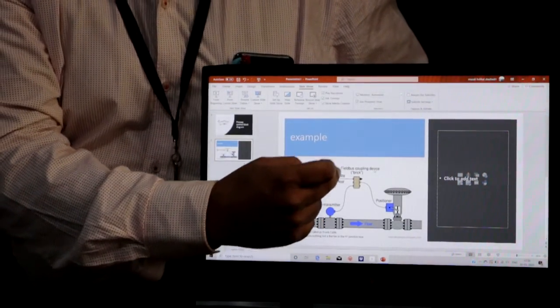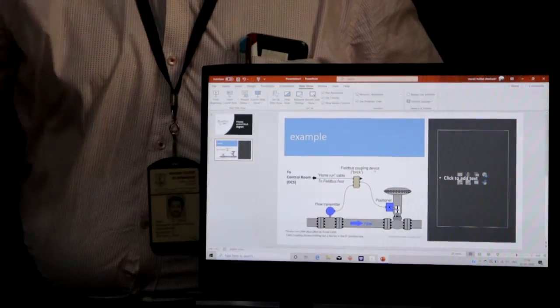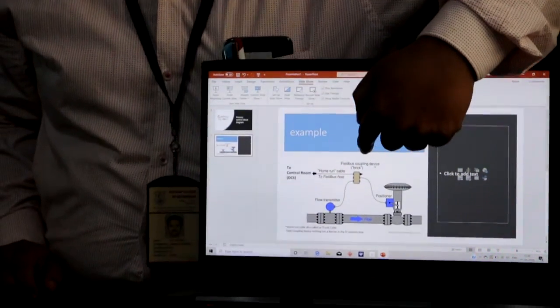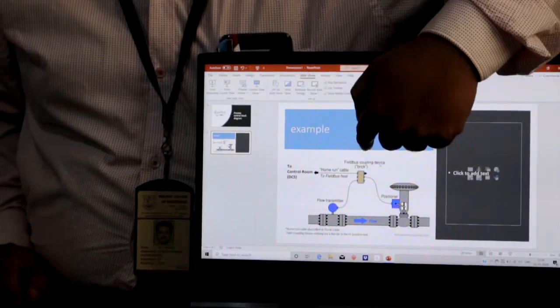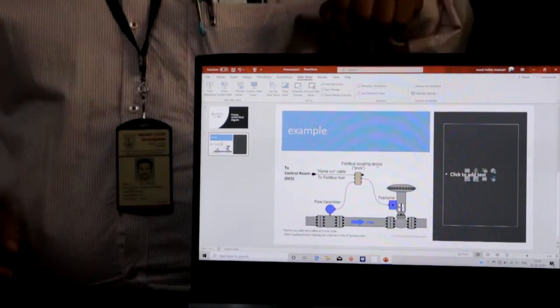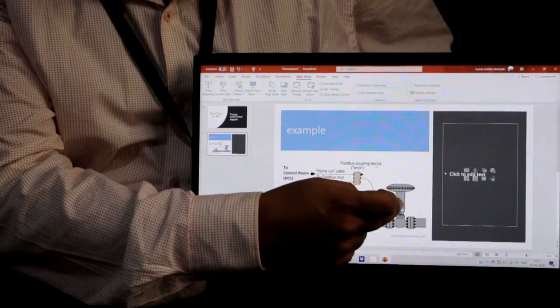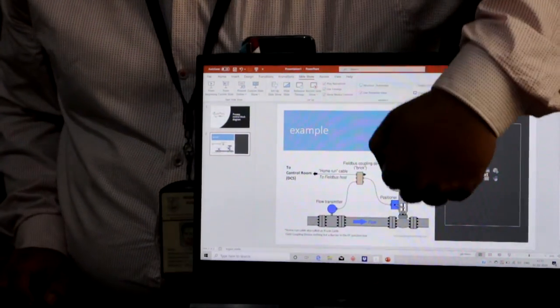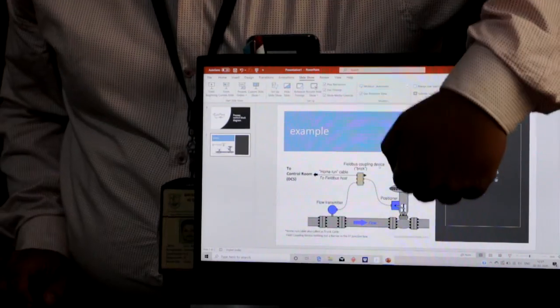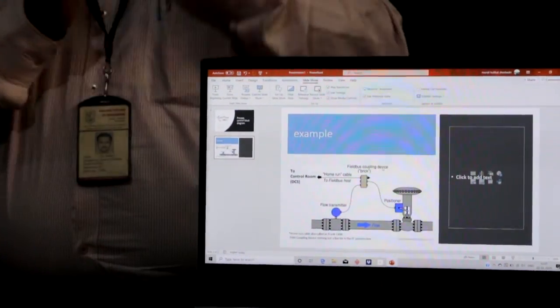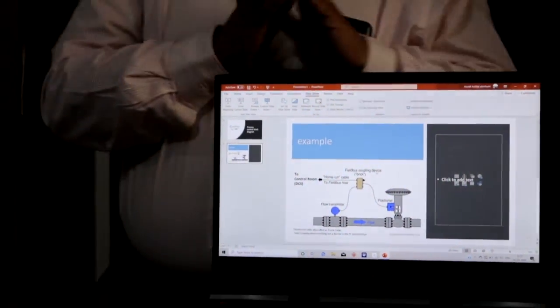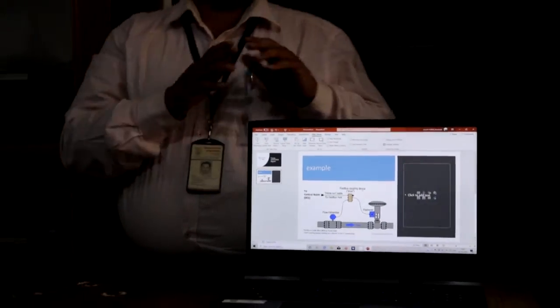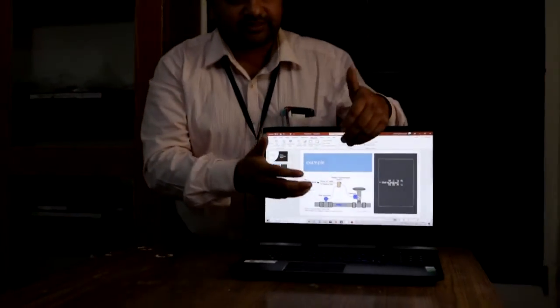This pressure signal will be transmitted and given to a controller as shown, and the controller will measure the value of flow rate through the pipe and send a signal to the actuator, which is a valve, a pneumatic actuator. The final control element will act on the process to vary the flow rate. This is one engineering example. We can have several engineering examples like this.